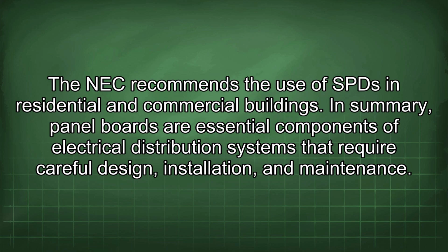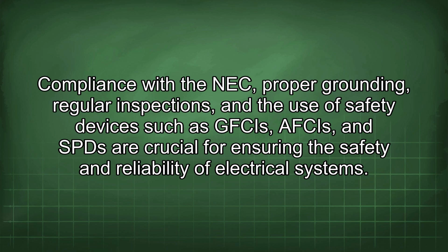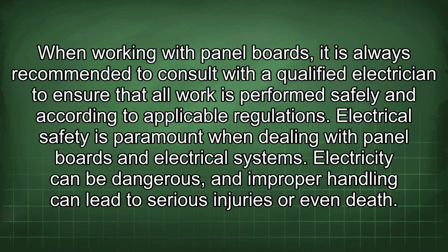In summary, panel boards are essential components of electrical distribution systems that require careful design, installation, and maintenance. Compliance with the NEC, proper grounding, regular inspections, and the use of safety devices such as GFCIs, AFCIs, and SPDs are crucial for ensuring the safety and reliability of electrical systems. When working with panel boards, it is always recommended to consult with a qualified electrician to ensure that all work is performed safely and according to applicable regulations.